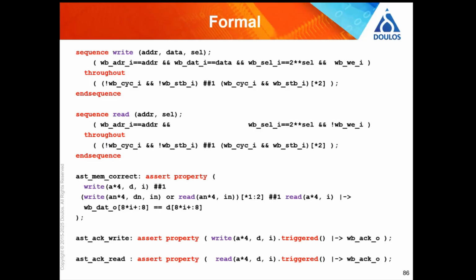And the key thing is the formal tool will prove that that is always correct, whereas the simulation will just do it for the particular address and data that you happen to choose. Here we said for all possible combinations of writes with another couple of writes and reads in between, and then a read, it should work for literally any data, any address. This is quite complicated. It has byte lanes, so you know it's anything.